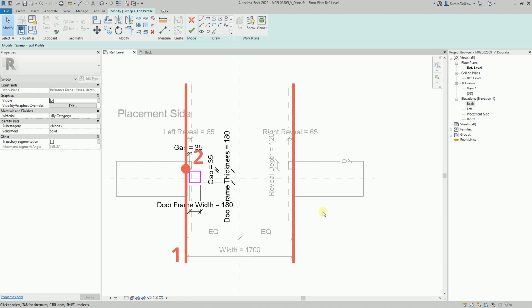Accordingly, the path sketch will move, the profile construction plane will move, followed by the profile sketch lines. If one of the lines didn't have a binding to the reference planes, it would stay in its position despite any changes, and the dimensions of the door frame would change every time the width or height of the door opening changed. But now, everything is connected correctly.